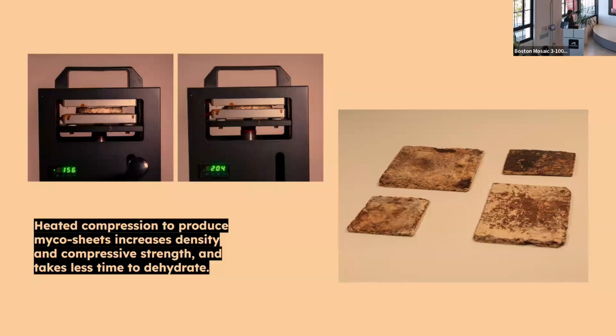I got a heated hydraulic press, and these plates go to about 200 to 300 degrees Fahrenheit. Using this in the last stage of the process, instead of dehydrating, we can compress and heat them at the same time. That reduces one step and makes the process way faster, because otherwise in an oven it would take 12 hours to dehydrate. Here it takes around half an hour, 40 minutes, but it does use more energy.